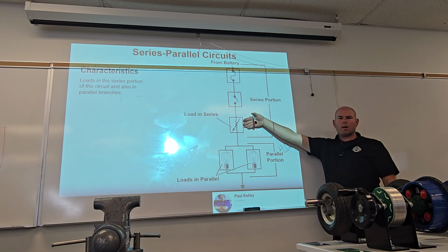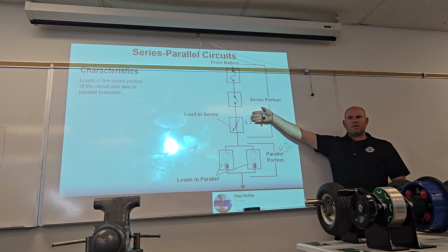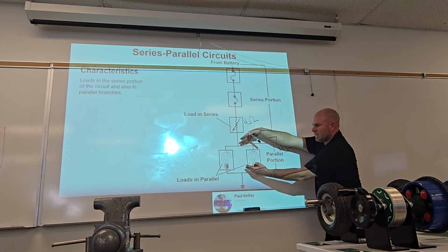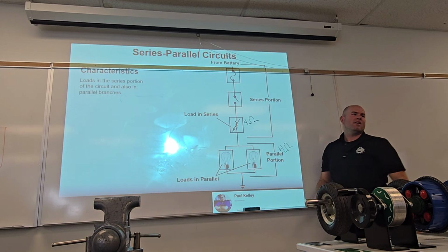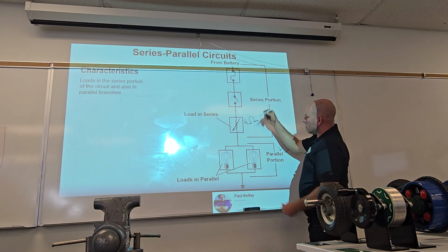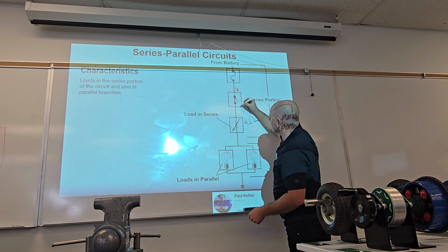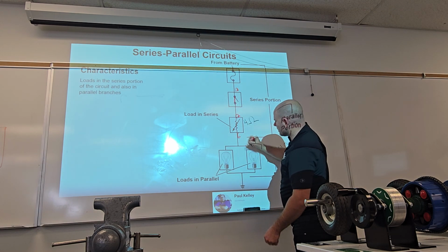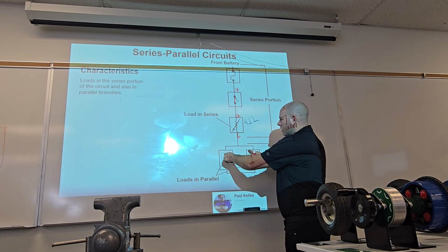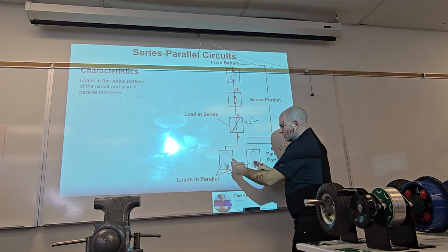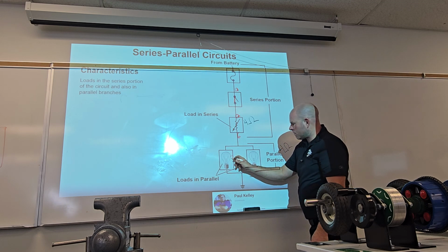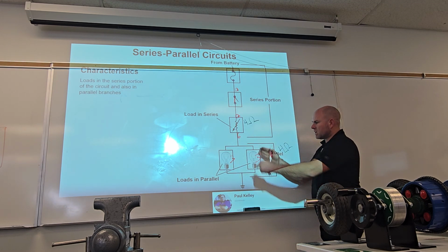What are we expecting to drop for voltage here? This has 4, and these two combined have 4. 6. Exactly, so we would have 12 volts coming in, the switch is closed, 12, 6, which means these both get access to the 6. These two don't share the 6, it doesn't become 3 and 3, right?